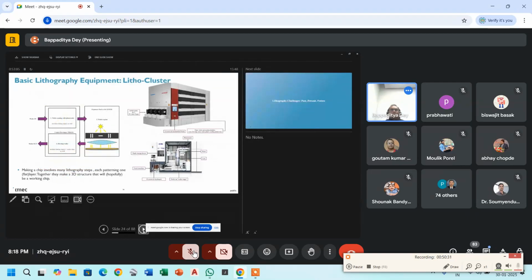So this is basically the tool I have shown in the video. Yes, this is the tool you have seen. These are your stages. You put your wafer, and this is the track. The track is basically responsible for preparing the wafer for being patterned. So here is a link; the wafer is coming here. These two are actually joined, and from the track it immediately flows into the scanner.